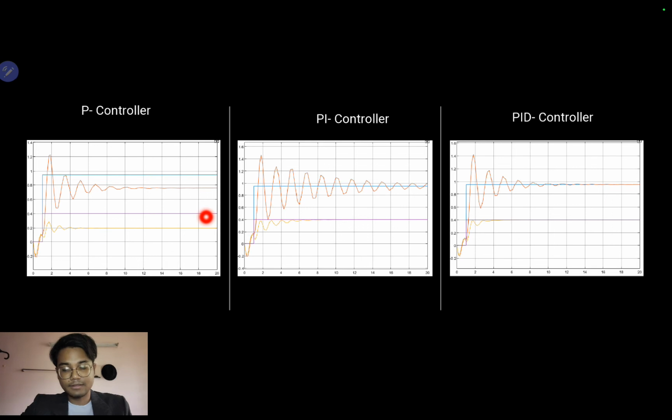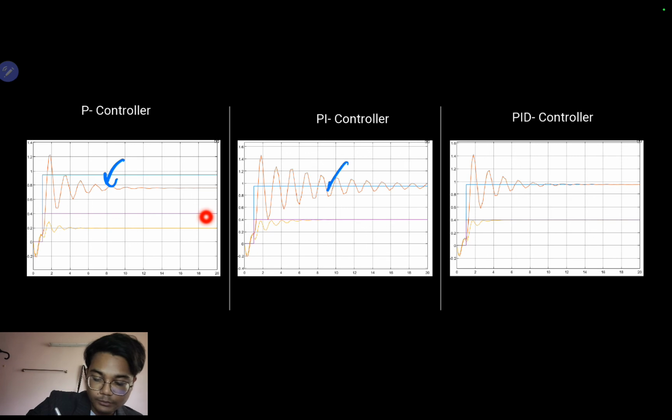Next, this is the value that we obtain from the Ziegler-Nichols method. As we can see, when we input only the P controller, which is 500, the graph that we obtained is right here, while for the PI controller, where we obtain P and I variables, we obtain this value here.